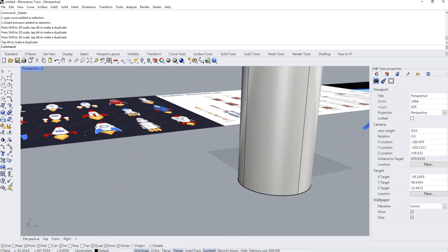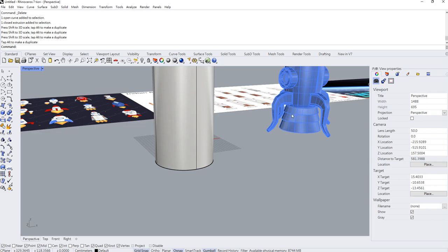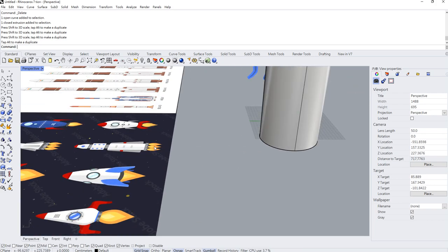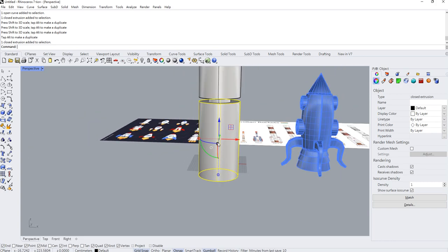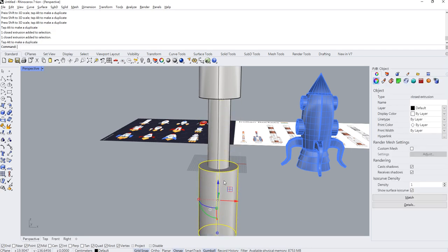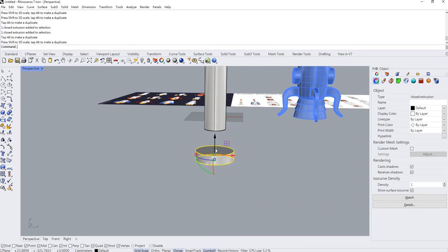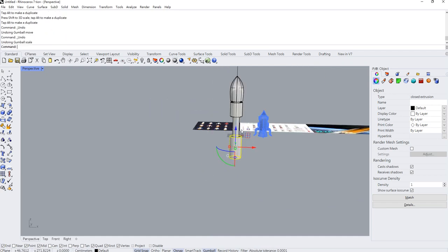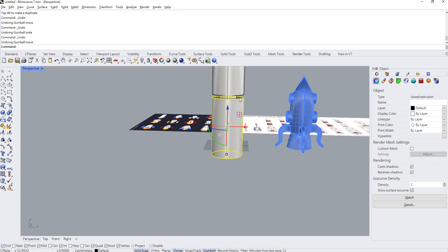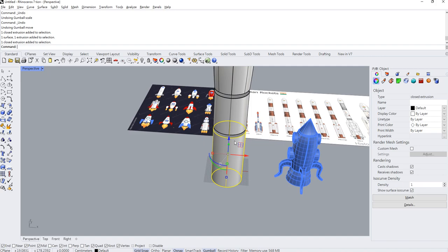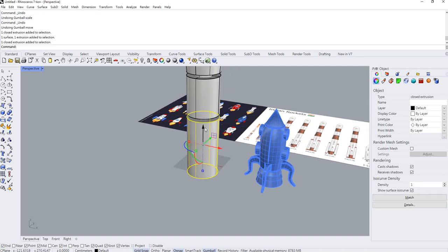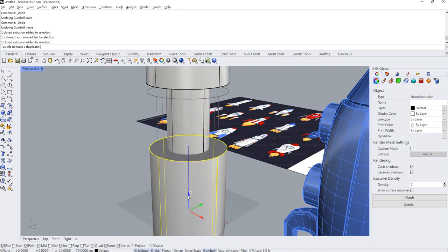And for the bottom area, they're supposed to have some injector on the bottom side. So how can we do that? Well, for sure I want to make some detail right now, so let's try to make more segments. Hold on shift and alt key, copy one more cylinder, make this one shorter, move this one up. Sorry, we have to use duplicate. Hold on your alt and shift key, move this one down.